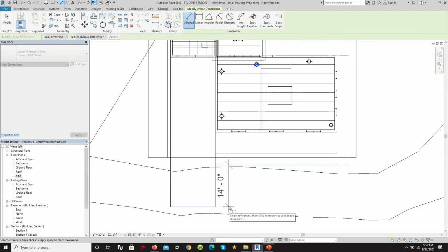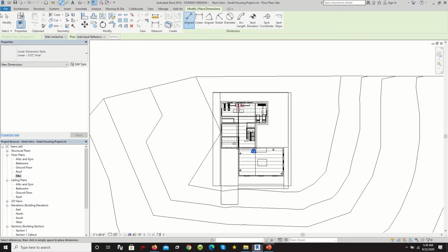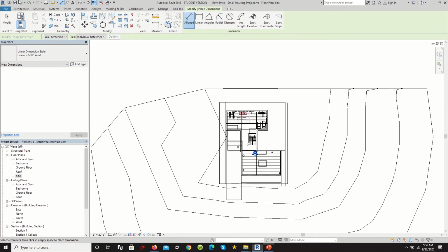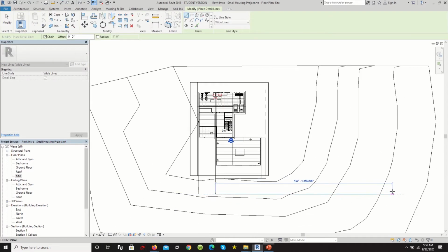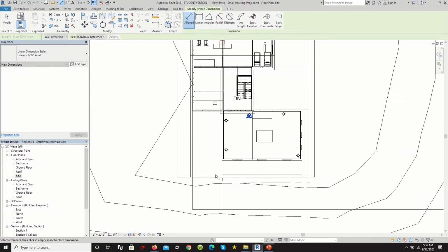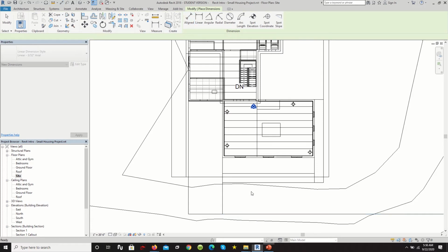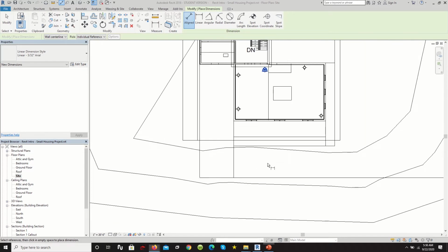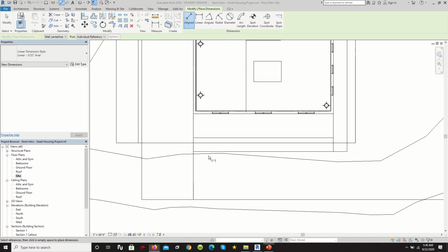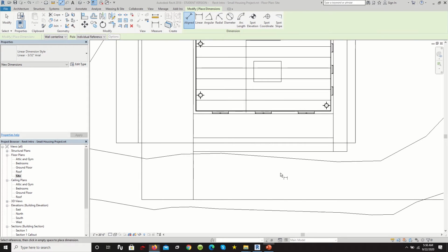What we'll do is we'll start to draw the sidewalk from here. First, let's define the boundaries of the sidewalk, the outer boundaries. So we're going to go back to annotate, detail line, and let's say that's the outer boundary, and let's copy that in. Typical sidewalk dimensions tend to be around 6 feet wide, but we'll just really make this wide, pretend like it's just like a huge mega sidewalk. So let's make this really wide.